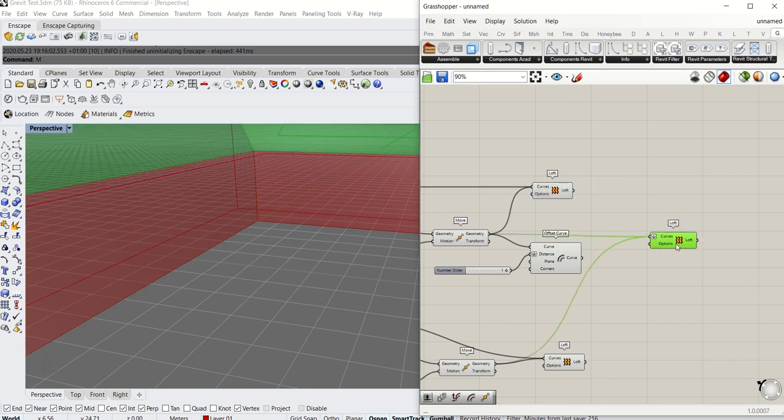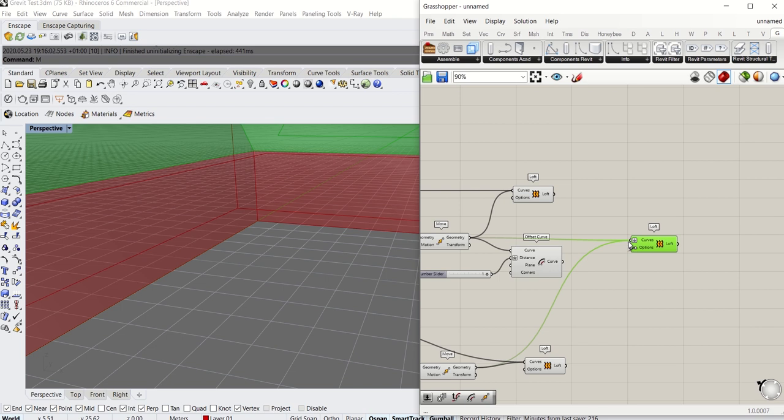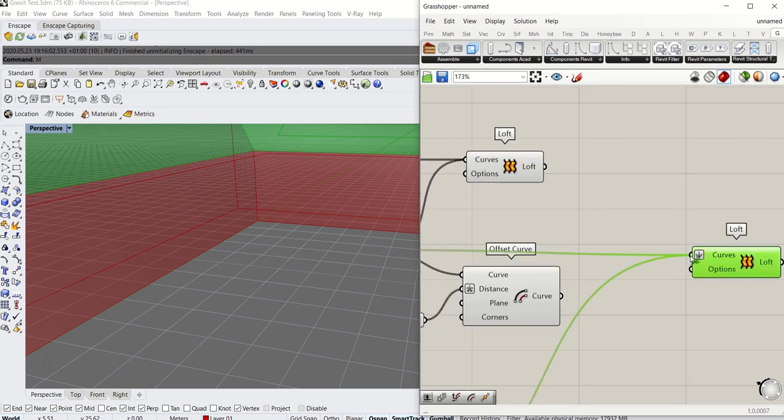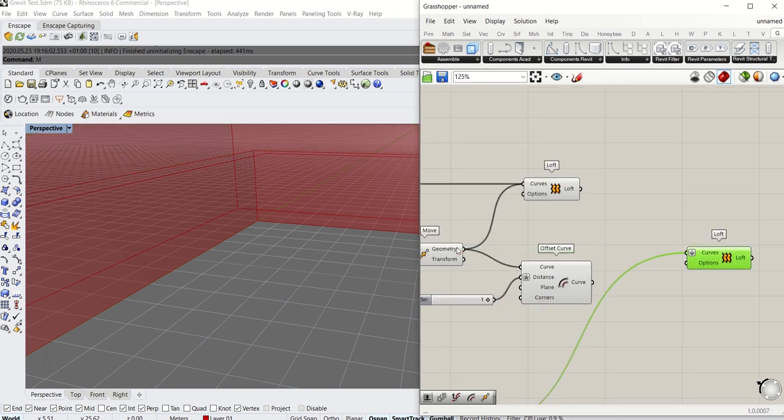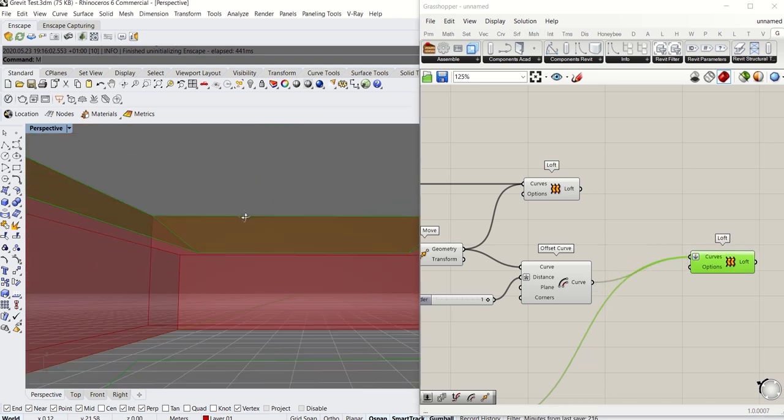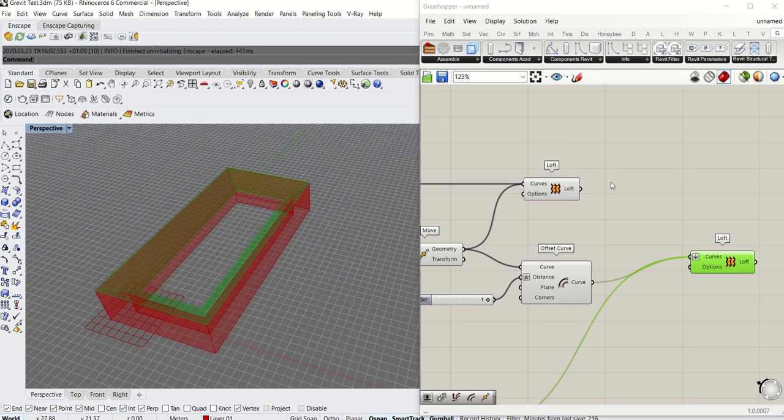You can leave that. So this is the pitch roof. What I'm going to do is disconnect that. Hold down Control and go back to geometry, and hold down Shift to reconnect to there. Now you have created an overhang of the roof structure.